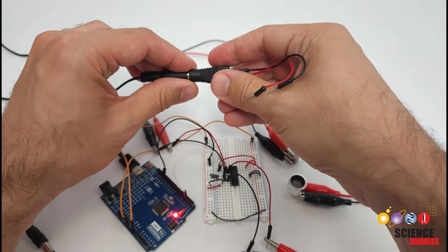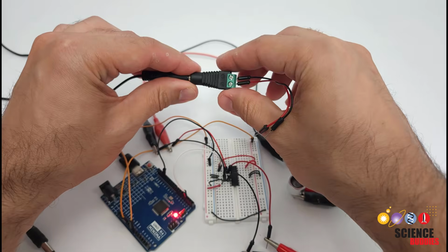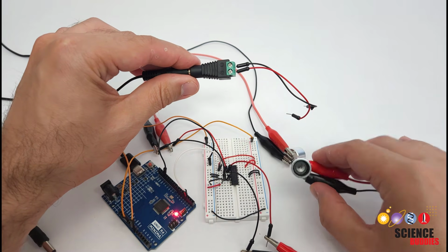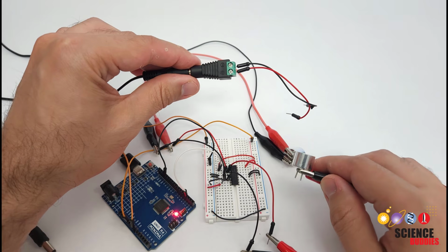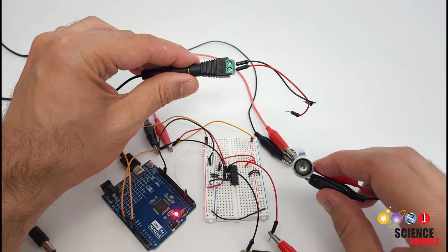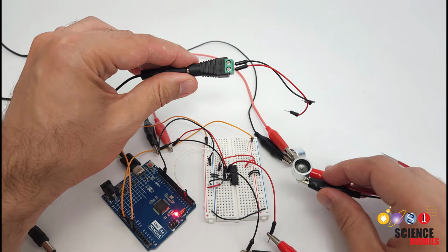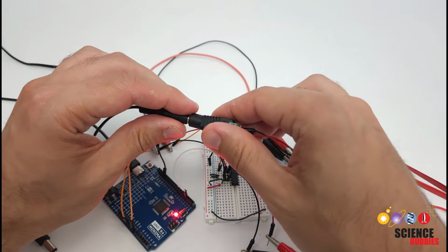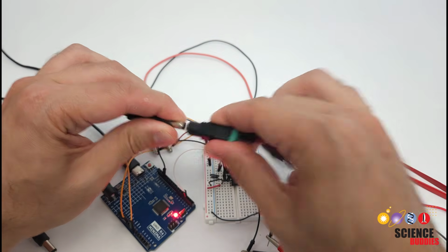So there is an option if you do get an even higher voltage power supply and you want to try driving the transmitters with a higher voltage. The other caveat there is that you need to check and see if you can find a datasheet for the maximum voltage your transmitters are rated for. I actually could not find that information with these, so I'm keeping it at 12 volts just to be safe for now because that got the demo working. Try higher voltages at your own risk.